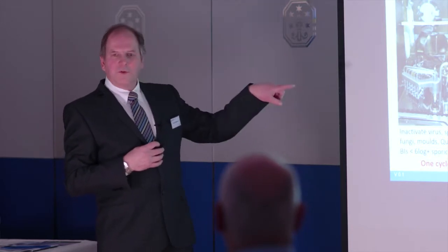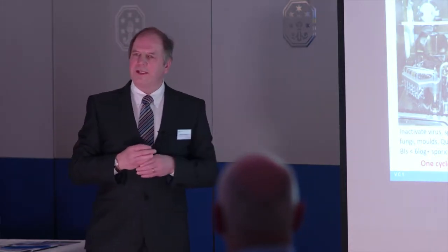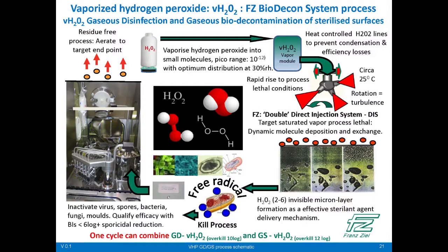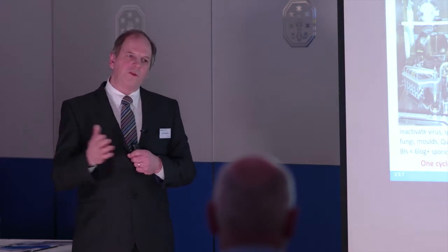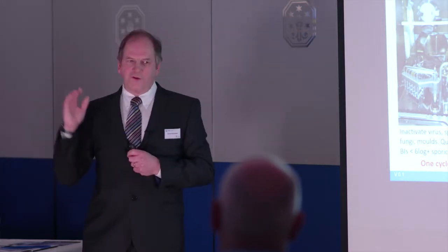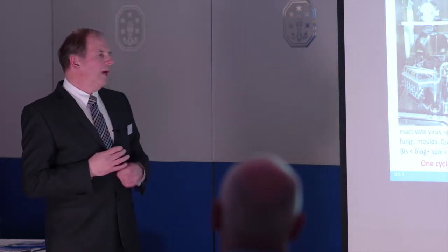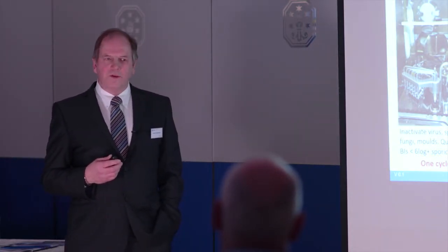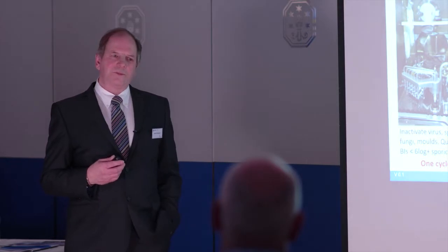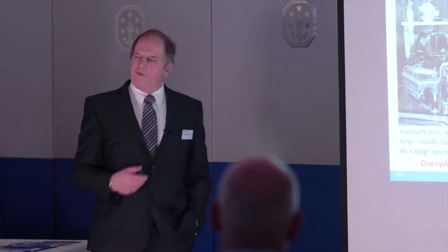After that, we need to focus on the aeration and the integration of catalyst cells. Now, we have impregnated cloth catalysts, which we use in our circuits. We motor them in and out of circuit, so we drive them into circuit when we require them and drive them out when we don't. It gives you local catalytic breakdown without the need for huge air handling systems to try and get the airflow up.